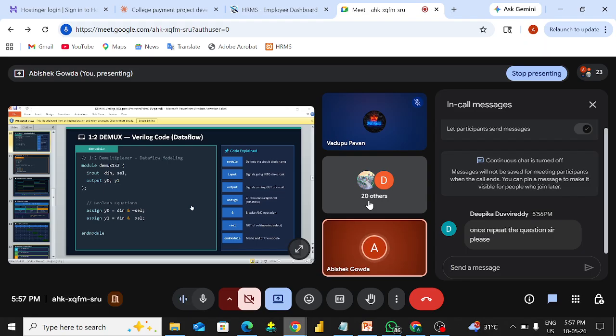After applying these steps, when you go to the tape out section, where you implement the design code you have generated as a hardware component for deployment, if you find a bug there, I mentioned that it will cost 100 times more than when you are at logical synthesis or while verifying in RTL simulation.